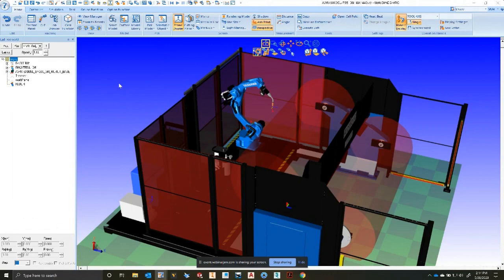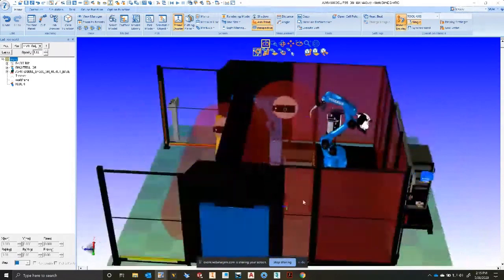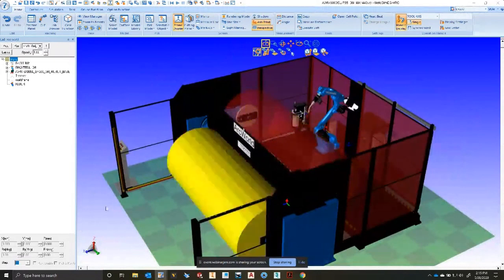And what you saw earlier is a variation of that. And you just drop your part in place and program the robot, and it will. You don't need to set the robot up. You may need to change the torch because your torch may be different from the ones in the simulation. But the hard work of getting the positioner configured and all the parts imported, it's all done. So this is actually quite handy. A lot of people ask for these.